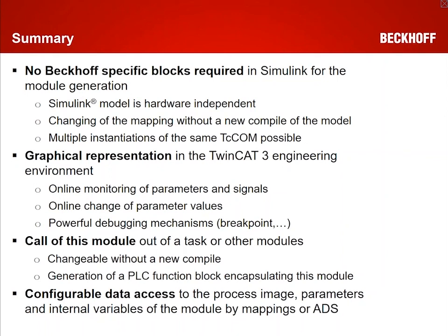We also provide the graphical representation of the model in TwinCAT 3, which you can use for online monitoring of parameters and signals. You can do online change of parameters, change also the startup values. You can debug using this graphical representation with breakpoints.